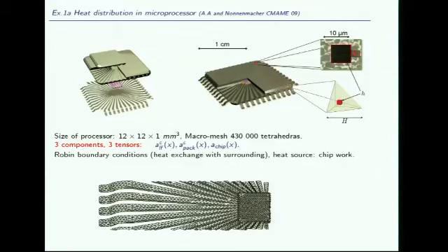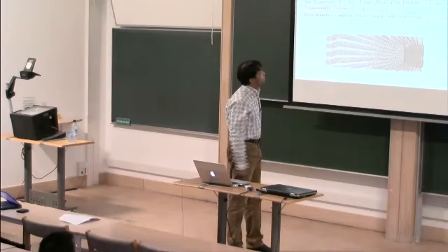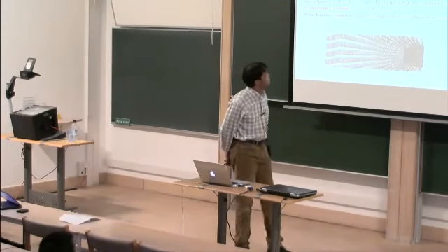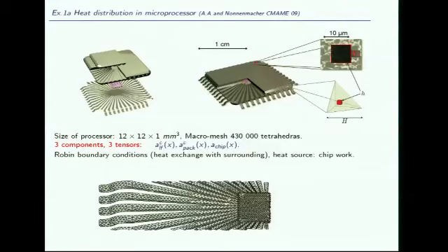Okay. So often, to have good properties of heat dissipation, the plastic package and the lead frame are made of composite materials. Okay, and that's typically depicted here. So these composite materials are, say, two materials mixed together, and the mixture looks homogeneous at the macroscopic scale. Here the macroscopic scale would be the scale of centimeters, but it looks heterogeneous at the micro scale. Here the micro scale typically would be of size micrometer.